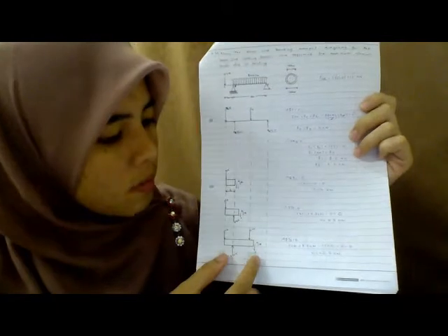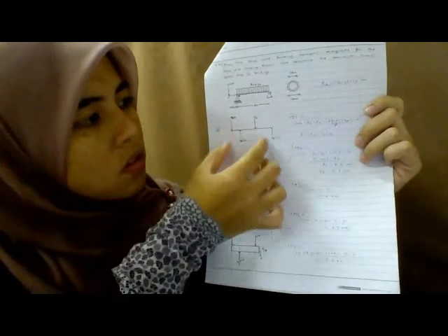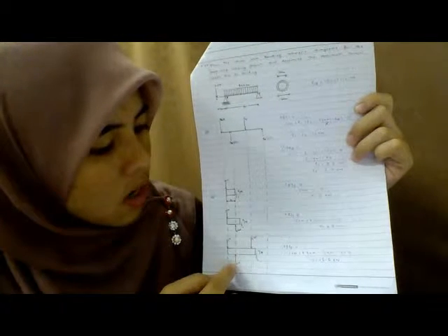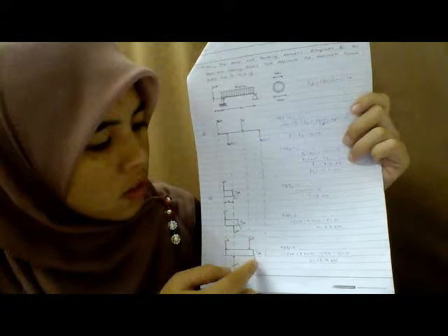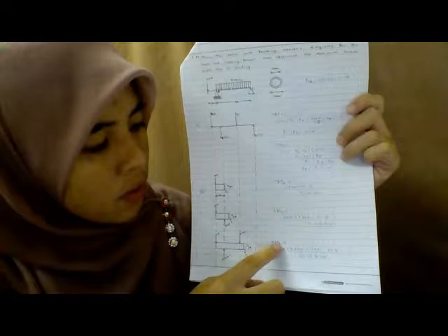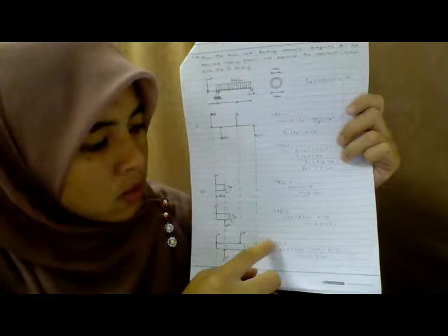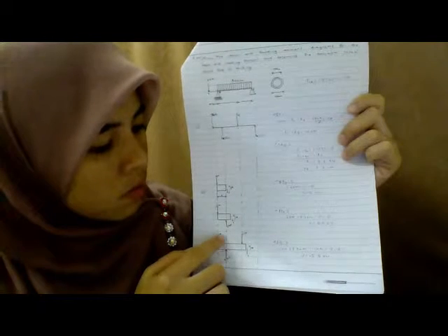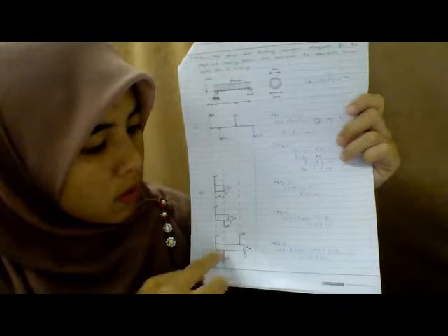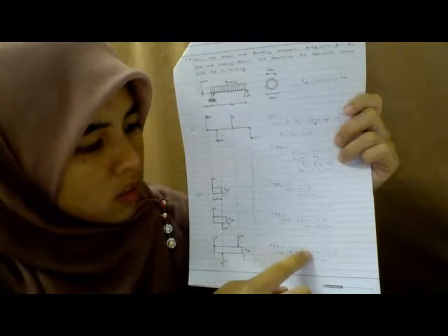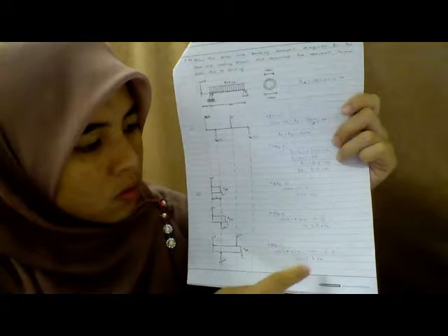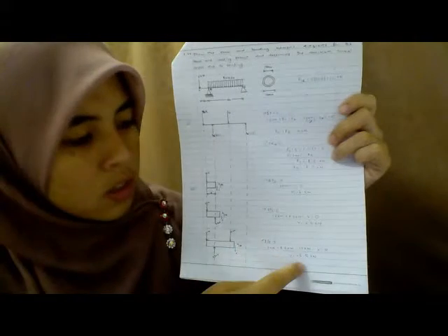And the fourth step is we take the third section here, and we have the force 2 kN, the RC force, the FCB force, and there is a value of V here. So we use the summation of Fy equal to 0. We assume the summation of Fy is in the positive way. So the value of 2 kN must be negative because it's going downward, plus 8.5 kN and minus 12 kN from FCB, and minus V equal to 0. So we can get the value of V here is negative 5.5 kN.